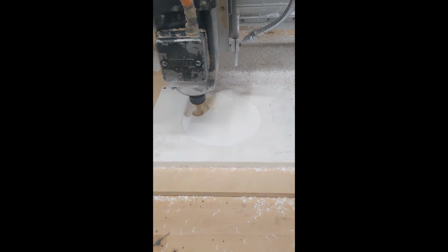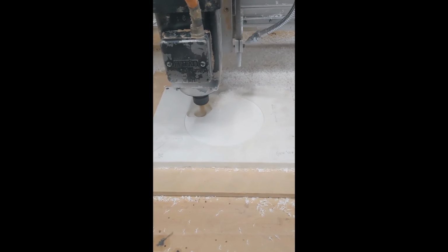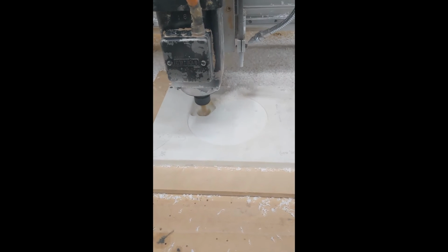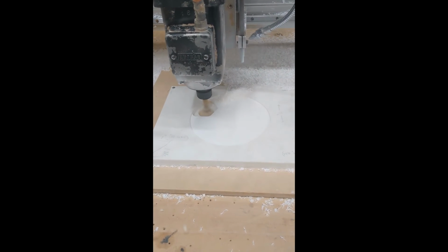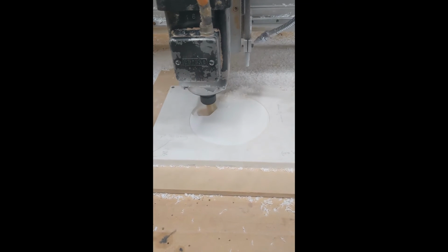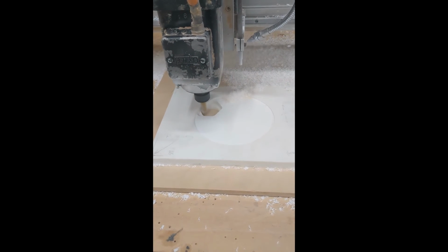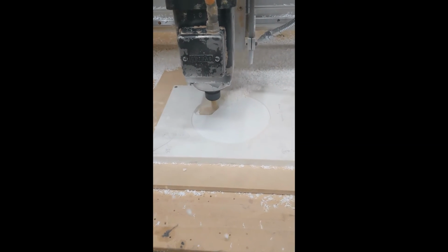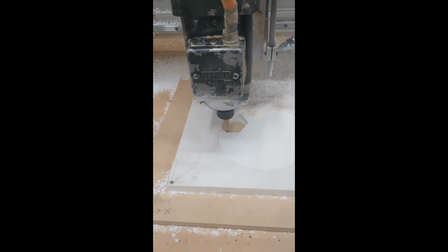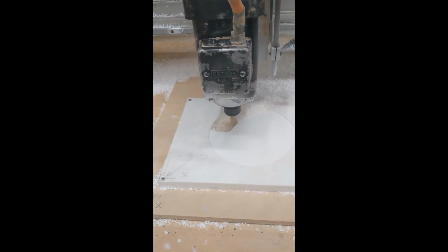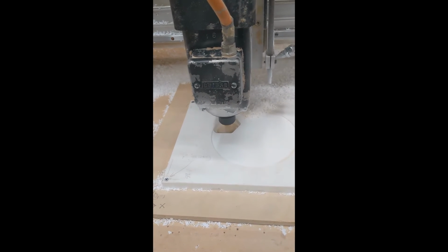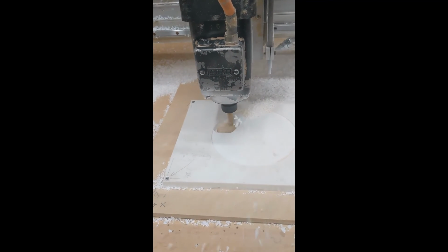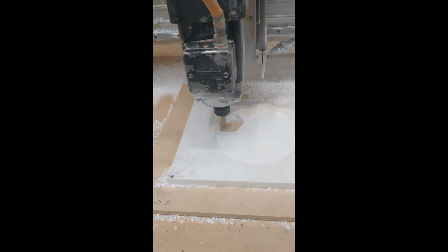Alright, this last little bit, right now I'm at 1 time speed. I think this is like about an eighth of an inch step over and like a quarter of an inch depth cut at like 50 inches per minute. So pretty conservative, but just to give you kind of like a sense of the speed of the machine.